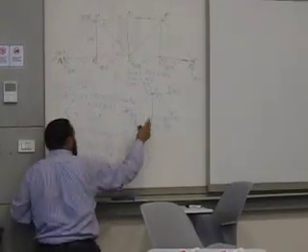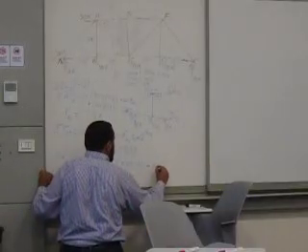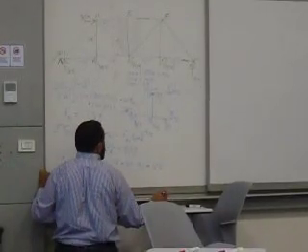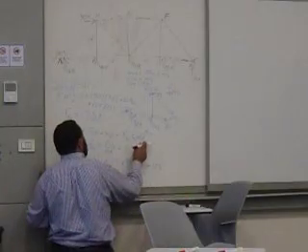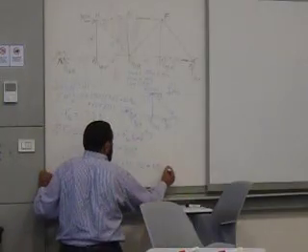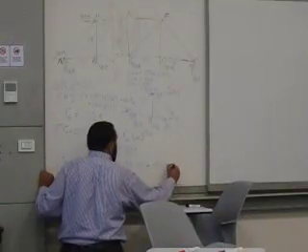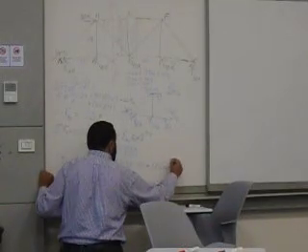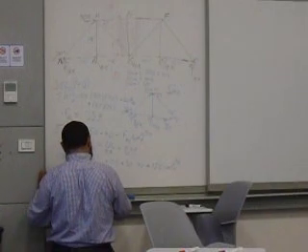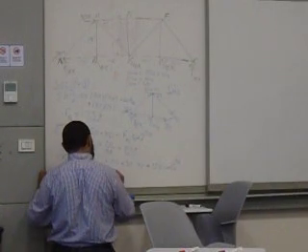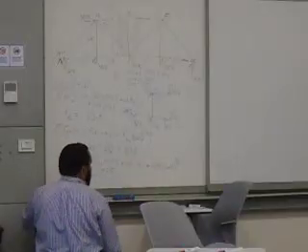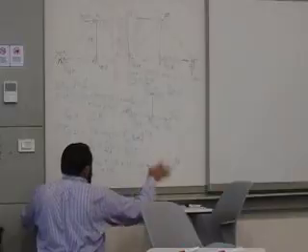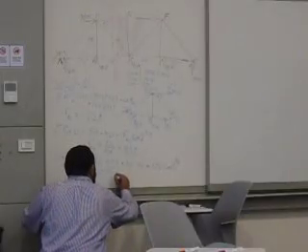Positive of the component of this. So positive of 12.5 times cosine or sine alpha. The vertical was sine, so the horizontal will be cosine. Is this clear? Therefore, FHG will be negative 15. Now these two will cancel. This will be 7.5 plus 7.5, and I'll send it to the other side. This is negative 15.